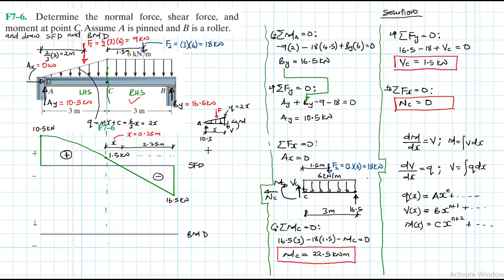And therefore, summing up the forces, summation of forces in the y direction, let's write what F is. F is equal to the area under that load diagram, just equal to half times Q, and Q is what? 2x, then times the length, which is x.